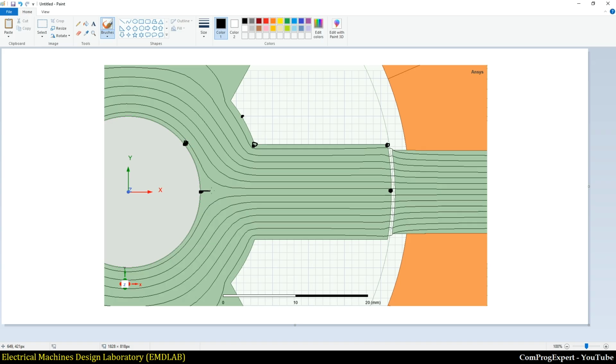Okay, so we can generate this geometry. Because of symmetry, we can generate half of one rotor pole. Then we can copy and mirror the mesh. That is an efficient method. I will explain.